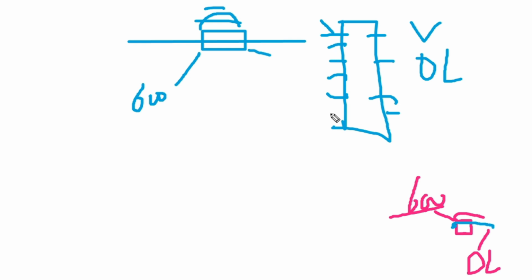Because when water logging or contact reaches the connector or this voltage line, the line burns, or you can say melts internally within the layers, right? That's why this resistance is also open. Sometimes you will see the other end of the resistance is also damaged, or there is no print, right?